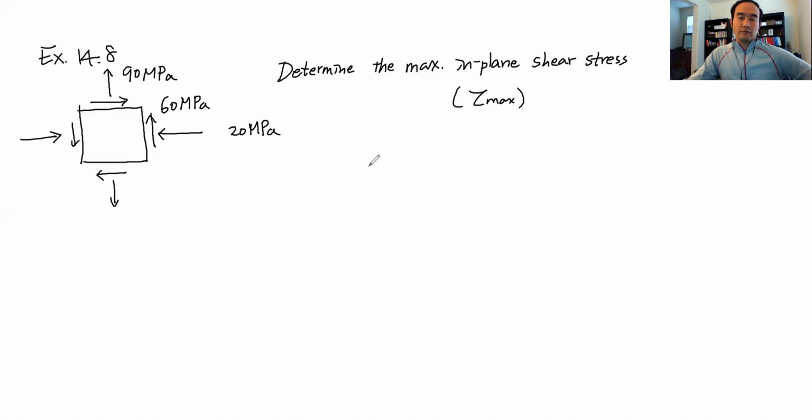So to develop the Mohr circle again, we have to start with how many points? 3 points, C, A, and G. Okay, so let's think about the coordinates of those 3 points. To do that, we have to identify sigma x, sigma y, and tau xy first, based on the given state of stress.